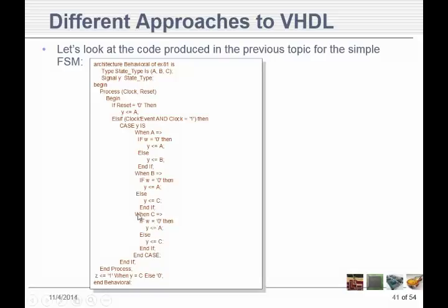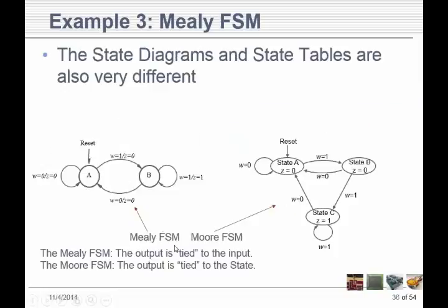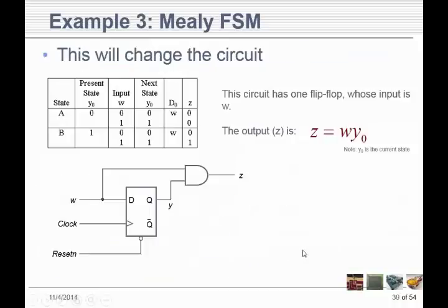And then I'm in C. If I'm in C, if W is a 0, then I go to A. Otherwise, I stay in C. To me, that is so easy to look at this and use that VHDL to come up with those cases. But that was this, not that one, because I have states A, B, and C. This one's only got states A and B.